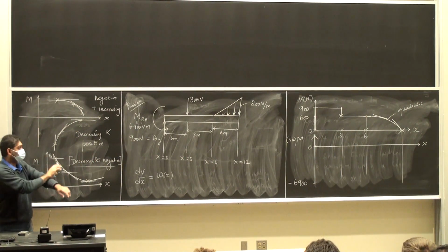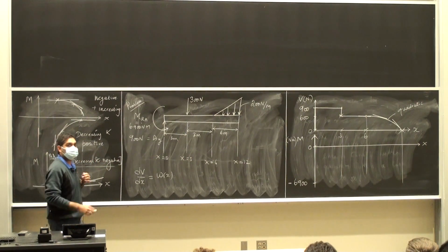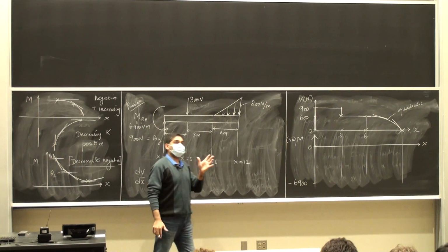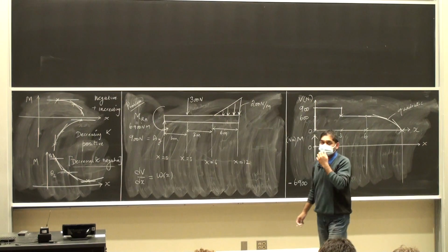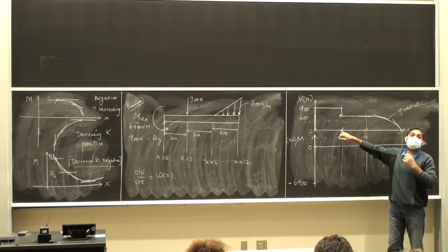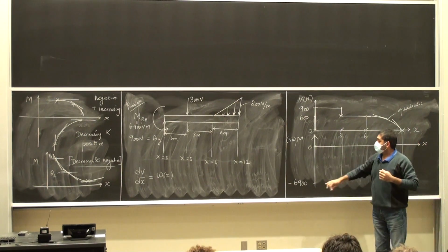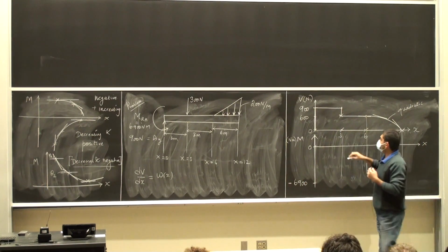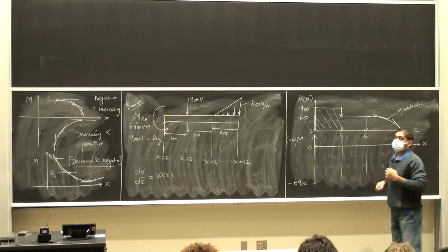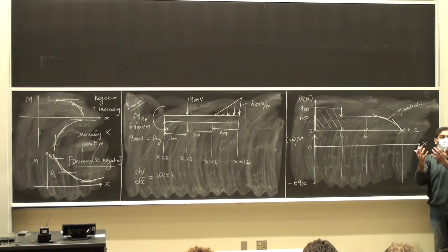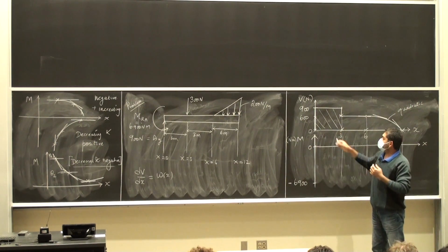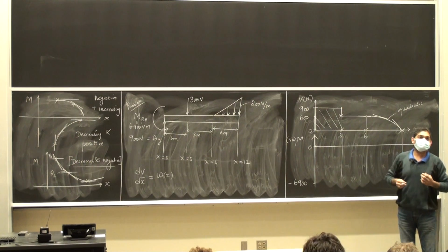Then how do I go from 0 to 3, and what's the value? The value of the bending moment at the last point that you are interested in, for example, if I'm now looking at the point 3, is the area under the shear force diagram plus this quantity. So the area here, all of that is a rectangular box which is positive. So that's going to be 900 times 3 minus 6,900.